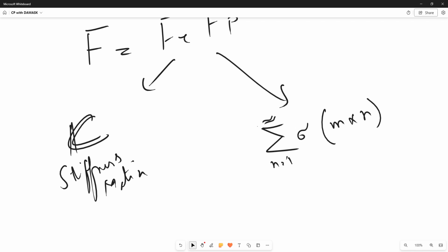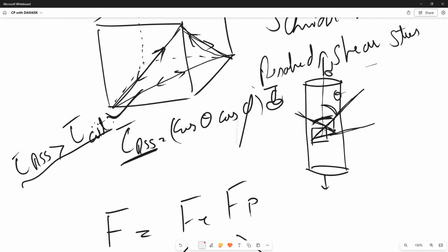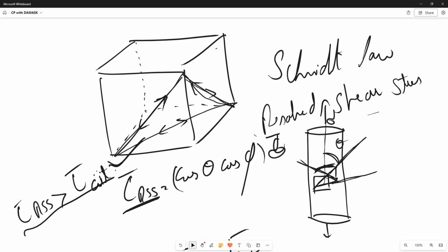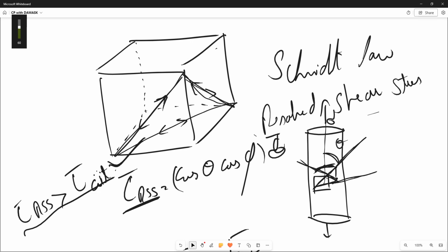Basically we combine the both and we get a total deformation gradient, which is a combination of the elastic part and the plastic part. Now in this plastic part, we can either define a very simple plastic deformation criteria, for example, a phenomenological law where we only find this kind of deformation, or we can have a more sophisticated or complicated plastic deformation law, where, for example, we define it on a more intrinsic level of what is the initial dislocation density, how the dislocations are moving, how they are tangled with each other, and then in the end, how hardening takes place, right?